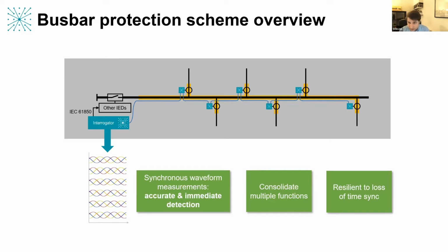With this kind of visibility, it's straightforward to do busbar protection, which is what we're performing, and that could be extended to consolidate other functions such as backup protection like breaker fail or overcurrent protection. Could all be integrated into a centralized approach, and it's also very flexible as well. We can quite readily provide the data to other IEDs as required if the protection functionality was required to be external.